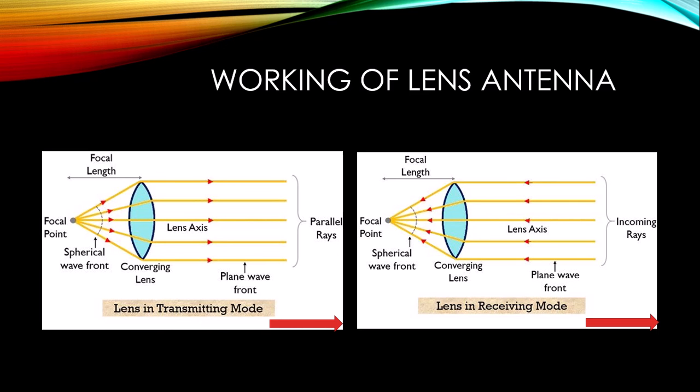In a similar way, in a lens antenna, the point source acts as the feed that emits the microwave energy towards the surface of the optical lens. This optical surface forces the radiated spherical wave fronts to change into collimated ones. In general practice, the collimating lens is made of dielectric material which possesses a definite value of the dielectric constant.